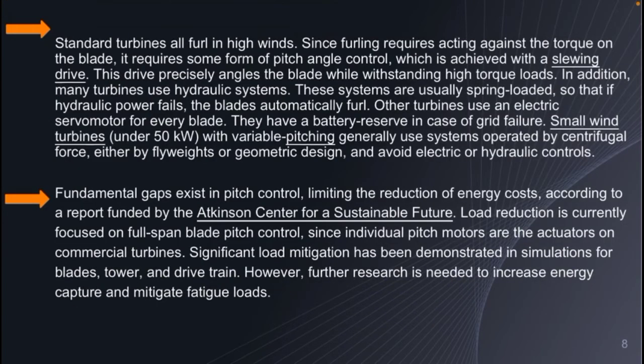Standard turbines all furl in high winds. Since furling requires acting against the torque on the blade, it requires some form of pitch angle control, which is achieved with a slewing drive. This drive precisely angles the blade, while withstanding high torque loads.